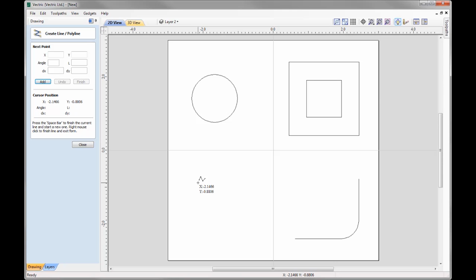In order for us to start to draw where we align our drawing to an existing object, we need to wake it up. To wake up an object, we simply run our cursor over the object that we want to wake up, and then we'll be displayed with various lines and extensions based on the object that we woke up.